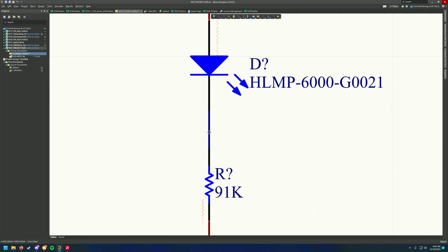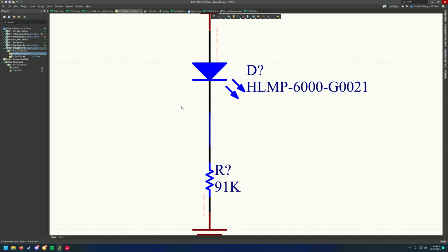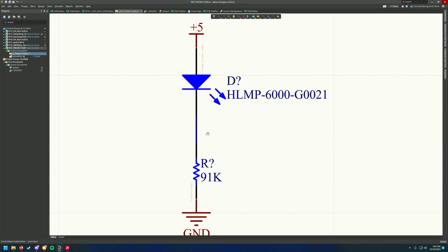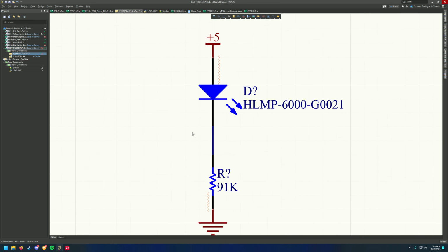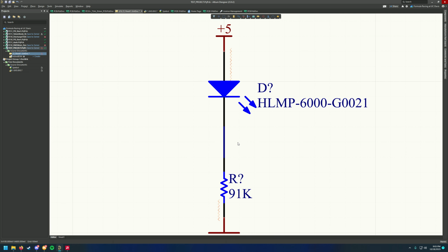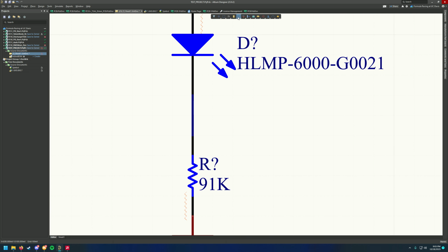So if you just place down a wire, Altium Designer will automatically name this. You can change that name, which is useful to do if you have a big schematic and you want to know what all these connections are. So the net label tool, so this is the wire tool, this little blue squiggly lines.